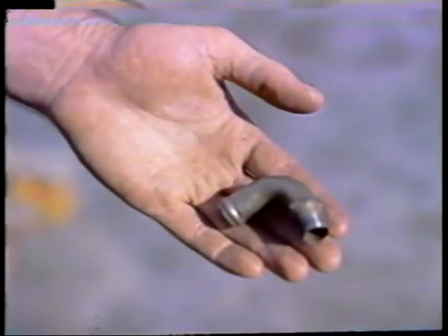To assure that the airflow through the system is not restricted, use only fittings and lines of the proper size and design. AN fittings are commonly used in fluid lines. However, their thick walls produce restricted bores, and the fluid flow through them must turn at right angles, creating back pressure or turbulence. The use of an AN elbow will often produce a pressure drop equivalent to 10 feet of the same size tubing.